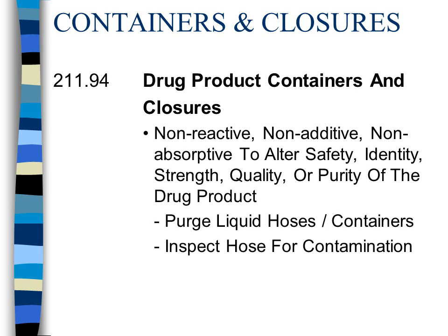When you're in the process of filling a liquid oxygen reservoir or a liquid nitrogen dewar, one of the things you want to do is purge your hose.